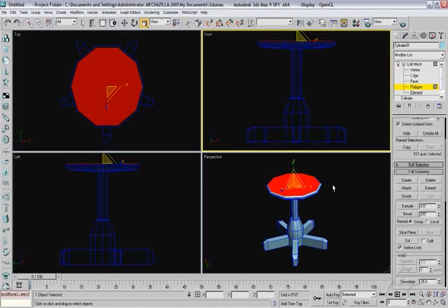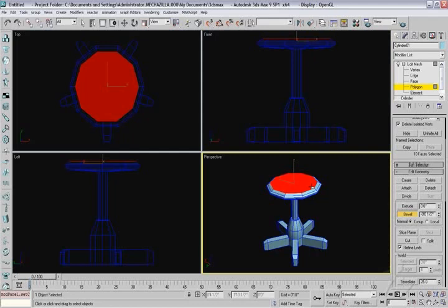At this point I've got some decent roundness going on. I could probably taper it 1 more time, but in our case that would probably be wasted geometry, but I will. I'll do it 1 more time. So I'll just pull that up, push it back down so it's about as much as the last ones, and taper it in. And as you can see, it makes a nice rounded edge for me. So the more edges and tapers you have in there, of course, the more rounded something will be. Once you've got that established, then it's time to move on to creating the extrusions for the pipes